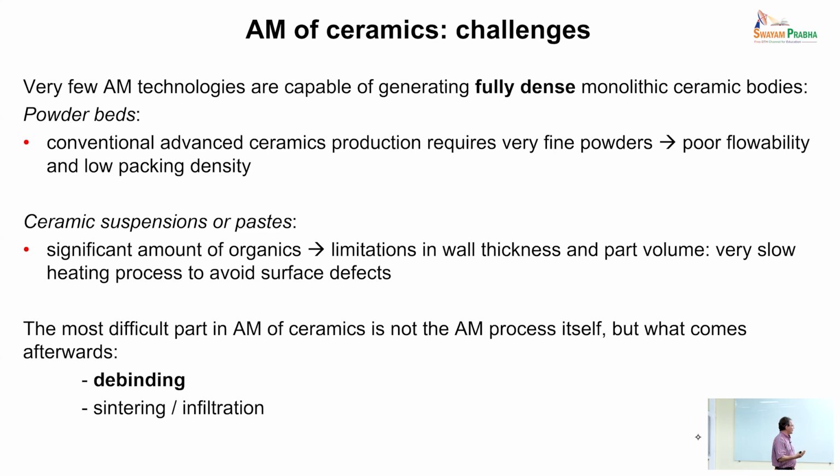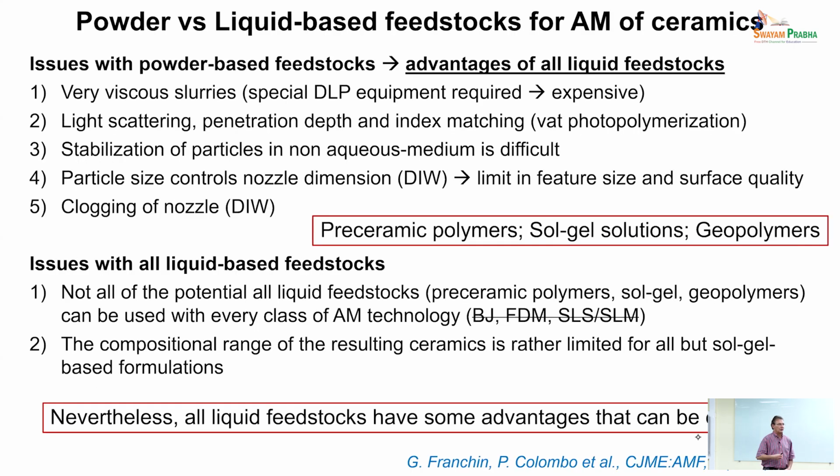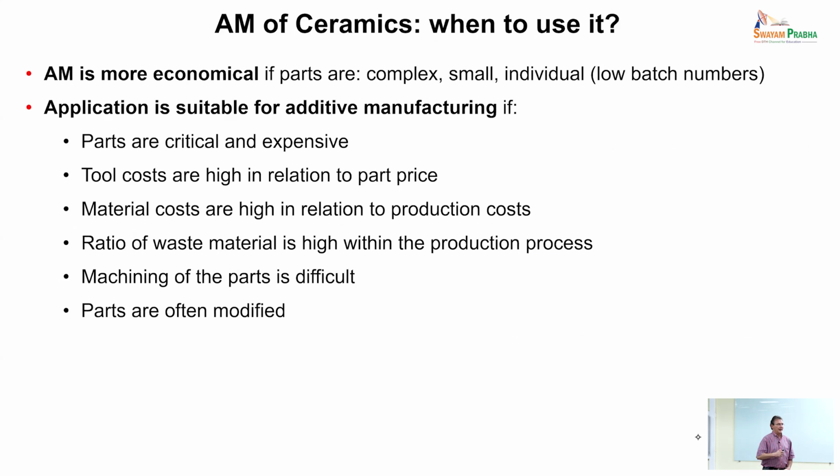In terms of challenges, certainly debinding is the largest challenge for additive manufacturing. This is common also for other regular forming approaches, traditional forming approaches, but the content of organics in feedstocks for additive manufacturing is typically larger, posing stronger challenges. This I will discuss later.